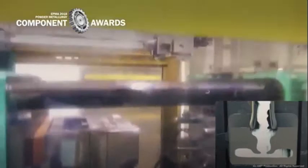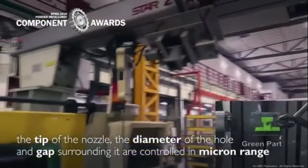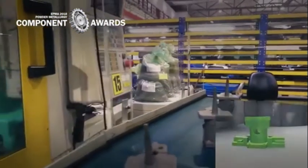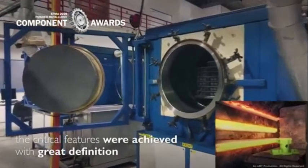The other critical feature is the tip of the nozzle. The diameter of the hole and gap surrounding it are controlled in the micron range, and are MIM'd without secondary operations. Looking at the cross-section, you will understand how the critical features were achieved with great definition.